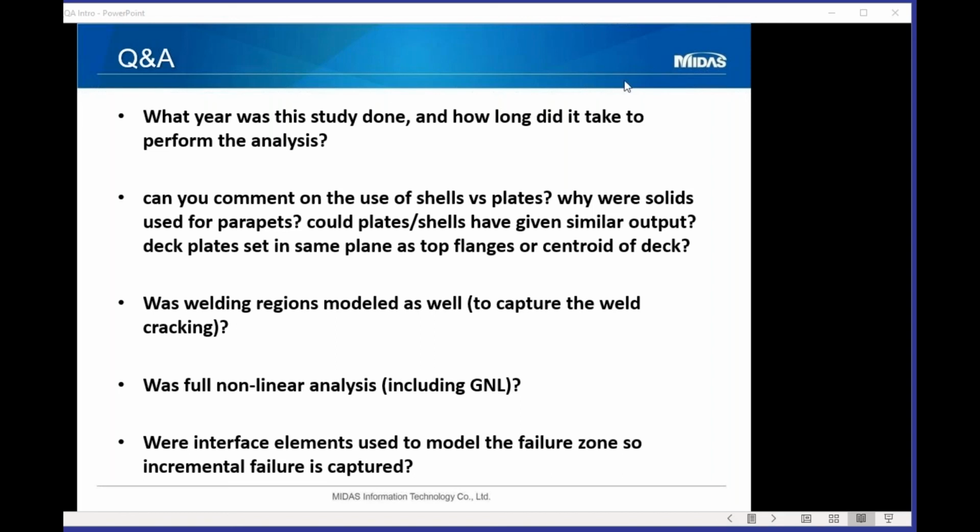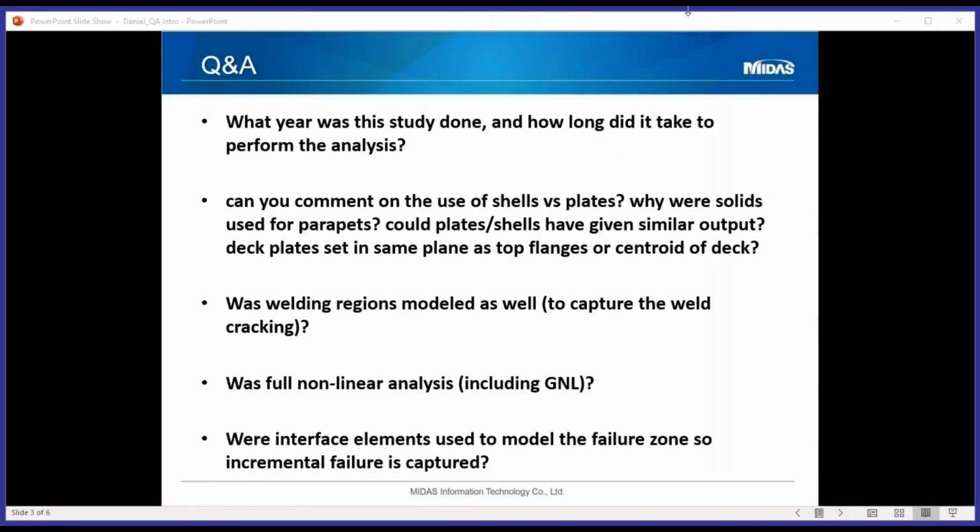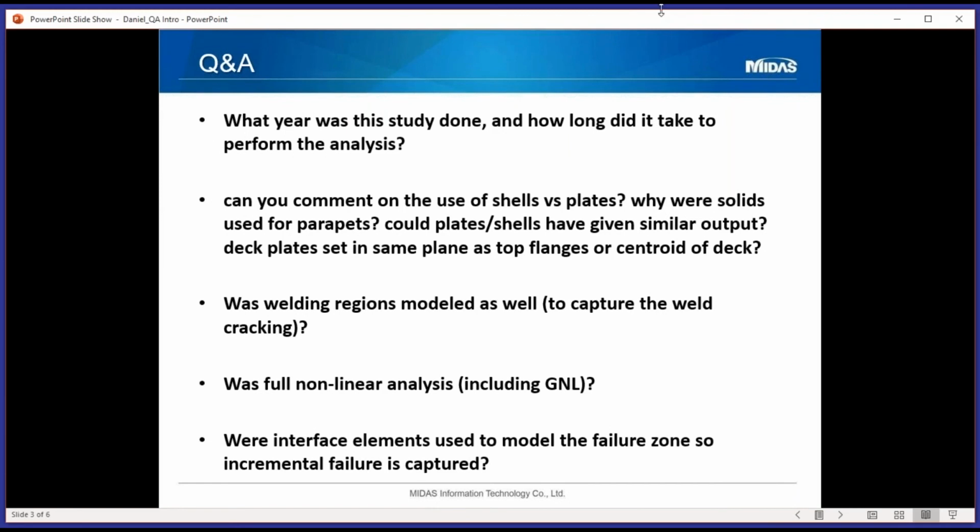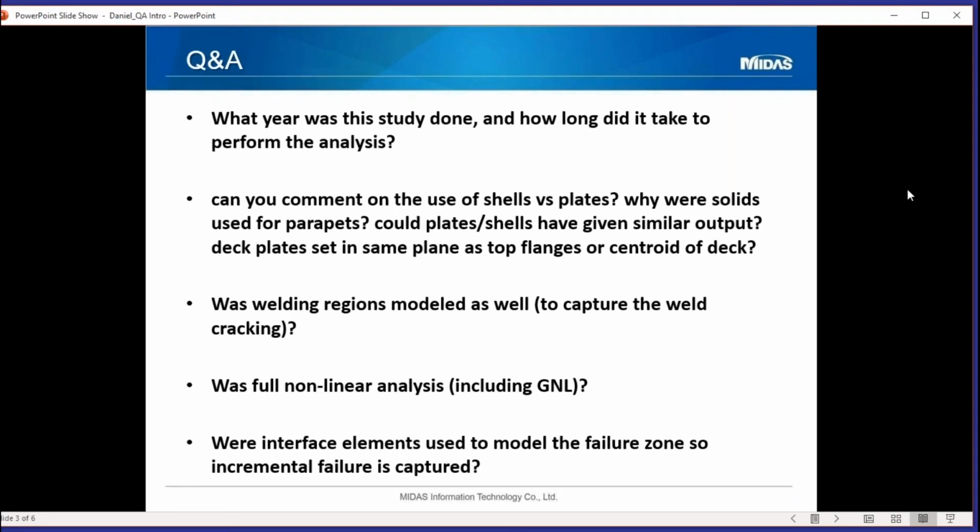In order to model the failure, we would unbutton each rigid link one by one, but in a symmetrical pattern, starting with the bottom flange middle node, and then going towards the webs. As the spring elements were unbuttoned, the forces on the spring elements were introduced back to the structure.